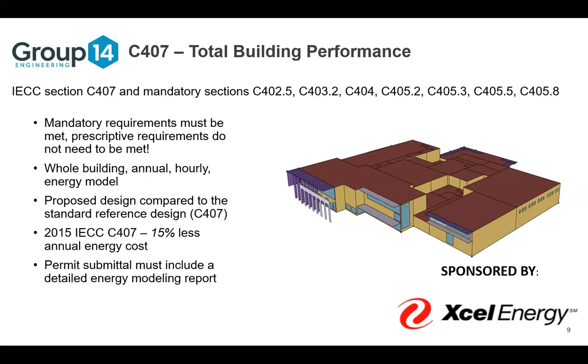They do not have to supply, in climate zone 5, we have R13 continuous insulation plus R7.5, or sorry, R13 in the studs, R7.5 continuous insulation. They do not have to meet that requirement. They can have just R7.5 continuous.